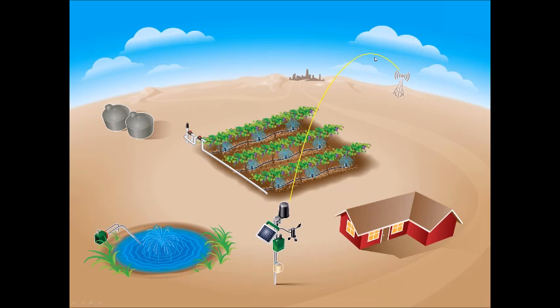So you can see here we have a little connecting line over here to the cell tower. Now the cellular connectivity for Ranch Systems equipment is crucial, so a good signal is important. Make sure that you have signal in your cellular device, like a cell phone, where you can verify that you have signal, and if need be you can install a directional antenna to boost the signal a little bit, but if there's no signal, something else needs to be decided as to the way to do that. Once this data has been sent out to the cellular network, which is the way that this unit connects, then it is sent to the cloud, or to the Ranch Systems server, where the data is stored.